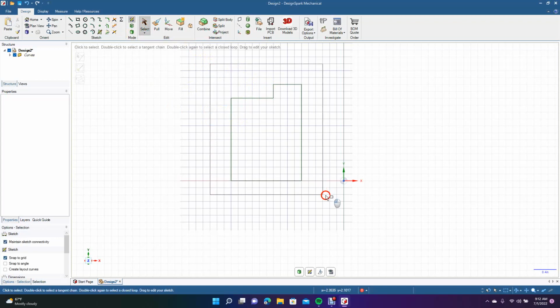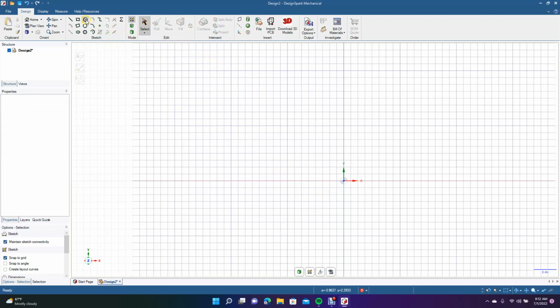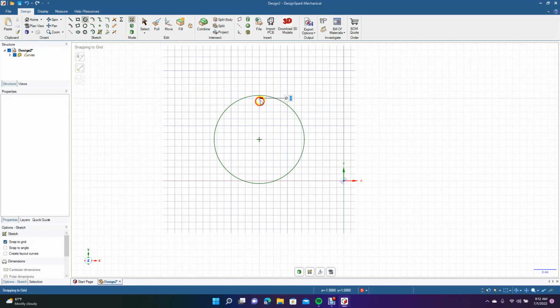Okay, this next piece here, trim away. This is a handy little feature. I use that quite often. And basically what that does is it allows you to trim away something. Like if you had overdrawn something, I'll just say like this, we'll go to here. So what you could do with that, as long as the lines are touching, you'll be able to trim away. So you could trim away these shapes here.